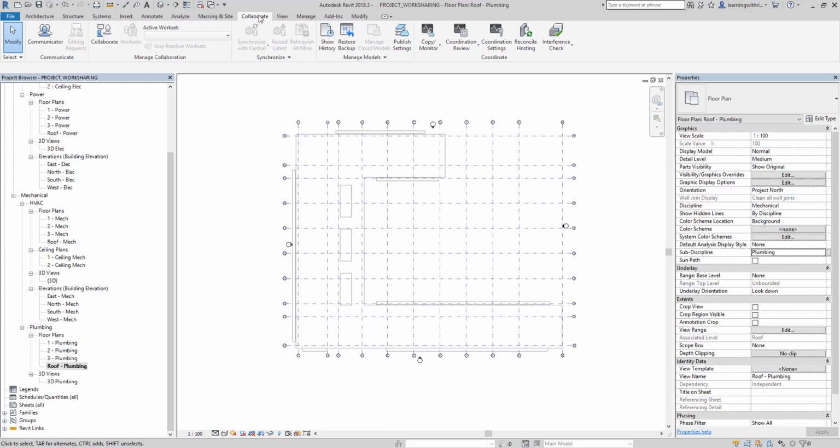So you can create a work set for interior, exterior, and site. And let's say, for example, for systems, you can also create work sets for HVAC, electrical, or plumbing, or piping, or fire protection. Okay, you can think of layers in AutoCAD. So in AutoCAD, you need to properly create your drawing, right? So you create layers.